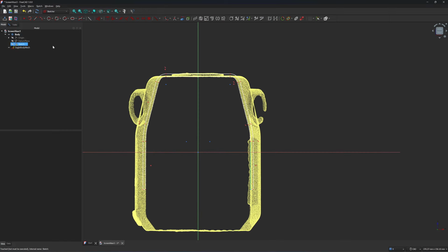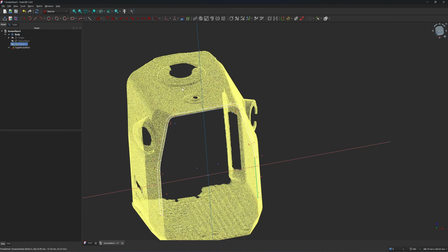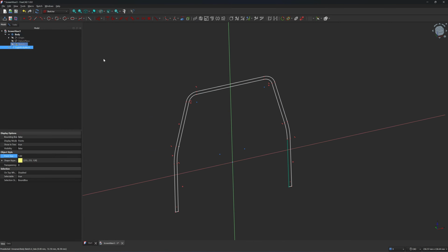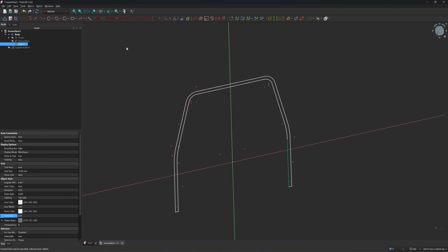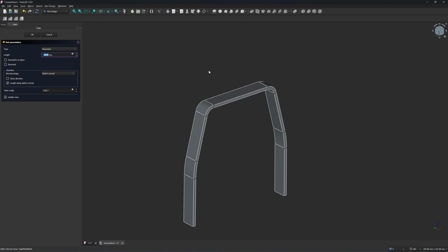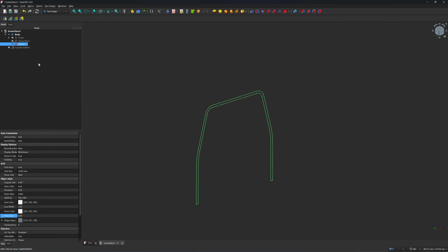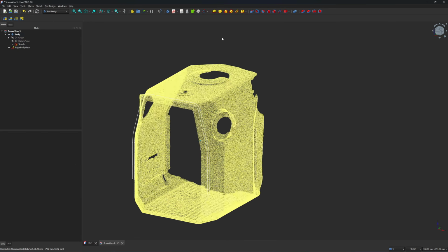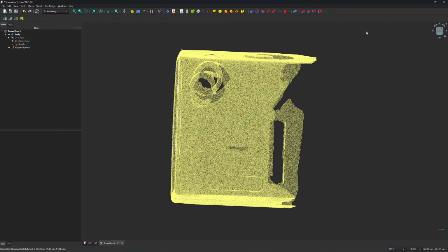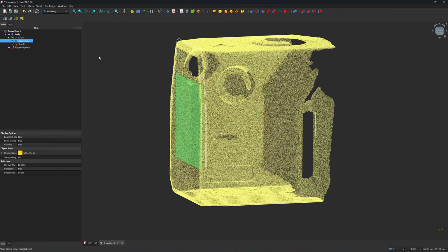Okay, let's test if this sketch has a proper closed loop. I do this by clicking on the sketch and click on the path command. So now I can extrude it, which means that it has a closed loop. Alright, so the first sketch is done. Let's create a second profile for lofting. Let me turn on the previous plane.